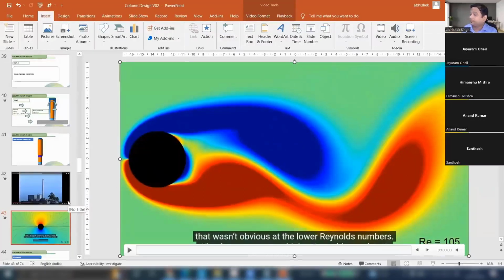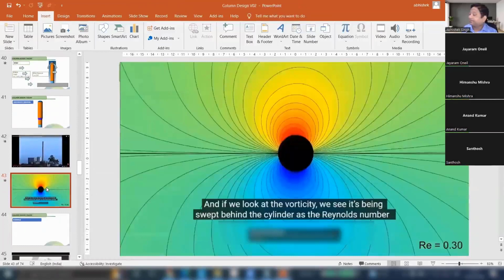Getting it? Yes, the red zone is very high pressure. So here what we are trying to say is the two different flows. That red zone is not like here it's blue, that is the other, left and right hand side. Because we want to see the different colors of vortices, that is the reason we have indicated two different colors. Making sense now, Amol? Is it clear how that wind-induced vibration is happening? Okay, great. Now guys, tell me, if there is an alternating force acting, what will happen?